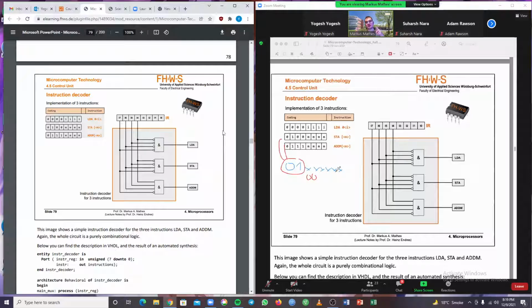And this means that this can be a different command, or the 0, 1 command with an operand. So that's a design problem. You have to prevent that a prefix or a substring of your encoded instruction appears in another instruction. And if you take a look at the previous slide, that hopefully is never the case in this encoding here. So you always get an unambiguous interpretation.